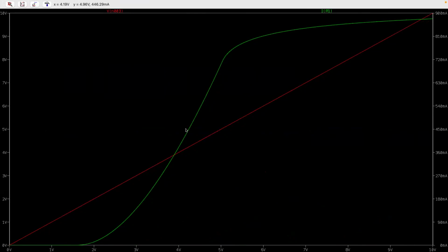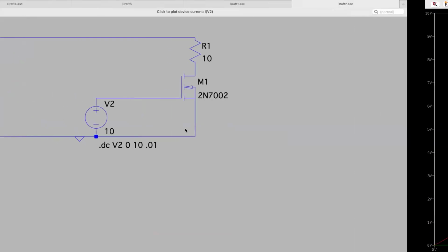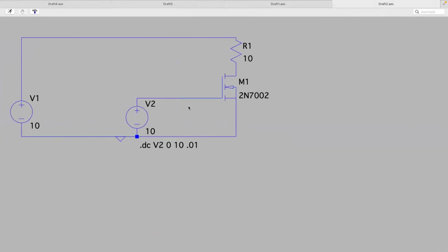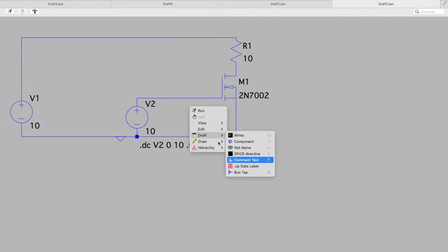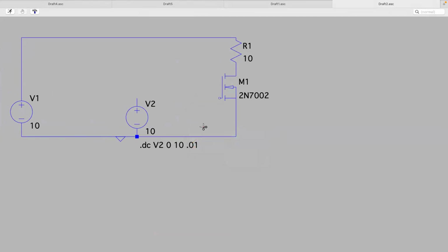Do you want me to show you what that looks like? Yeah. Cool. Okay, so what I'm going to do now is delete this line here in order to put those resistors in. There you go. And then I'm going to just type in R, put in a couple of those, and it looks like I have enough space. And then I'm also going to include a capacitor just to make things a little bit easier to look at.